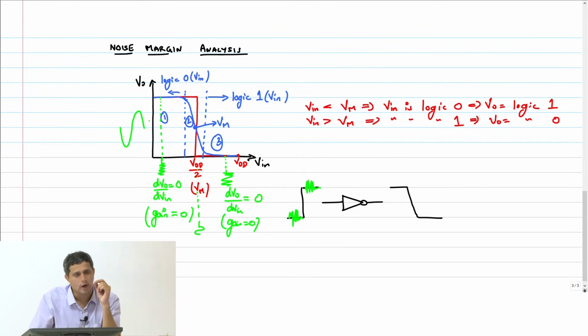Right? So the point is, as I am moving from left to right, my gain is going through some changes. If you adopt this definition that noise should just get killed in order for the inverter to be robust, then the region of transition where below some level it is treated as logic 0 and above some level it is treated as logic 1, what should be the transition value for the gain when I go from region 1 to 2, 2 to 3? What do you think this magic number for the gain should be?